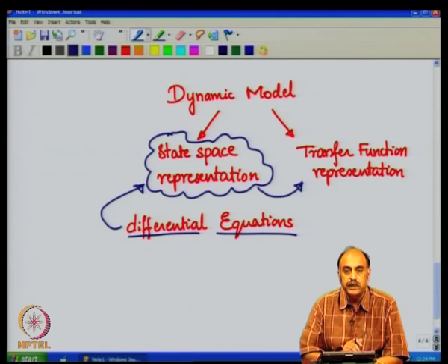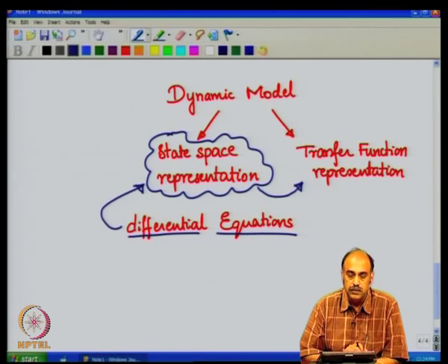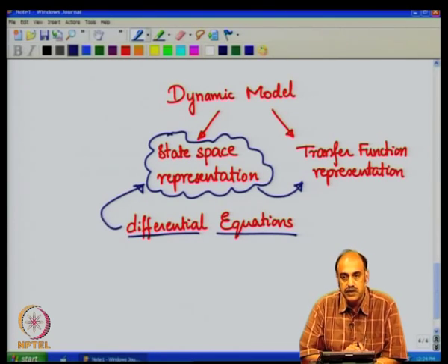Before we go into obtaining the state space representation of a DC-DC converter, because a DC-DC converter is a switched power converter, it has switches which are nonlinear in nature in the sense that they have two states. Superposition principle may not be directly valid. We shall look at a generic method for first obtaining the state space representation of a general plant, and then we apply it to the specific and special case of the DC-DC converter. So, let us look at the case of a general plant, wherein